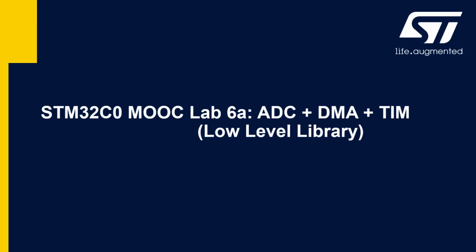Hello everyone, welcome to the Lab 6A of our STM32C0 MOOC. This lab is the equivalent of the Lab 6, which has been implemented using the hardware abstraction layer. In this lab, we will use the low-level library. The low-level library is a unitary service function provided by STMicroelectronics, making the access to register easy. Hence, the optimization regarding the code size and the performances of the application.